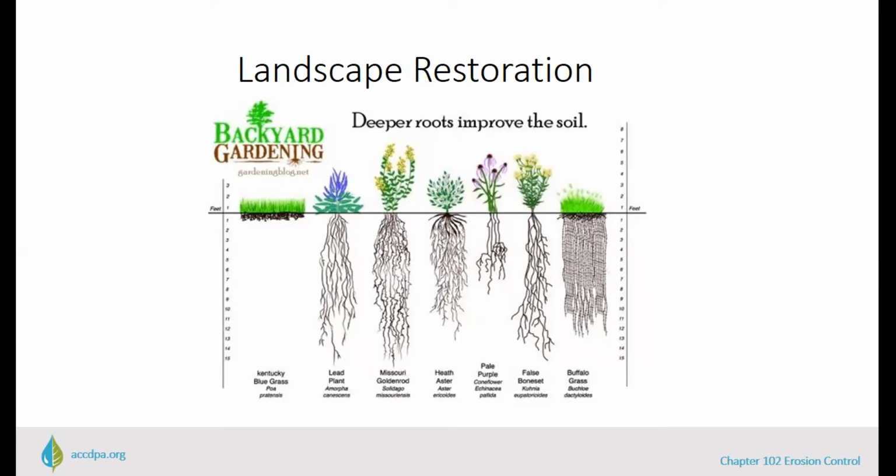Using this BMP involves some serious site preparation. The pavement had to be removed from that 3.5 acres. The subsurface was scarified and decompacted, and topsoil was brought in to prep the area for planting.